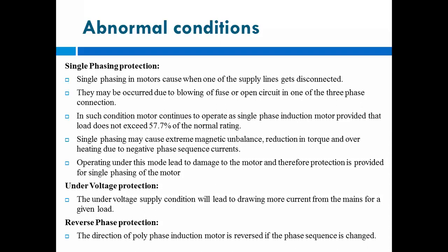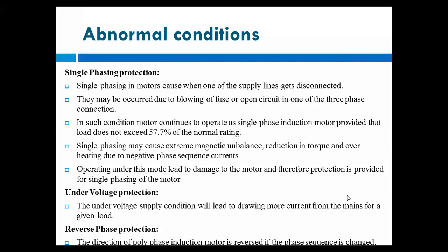And next is the reverse phase protection. Okay, so the direction of a polyphase induction motor is reversed if the phase sequence is changed. I think you have seen the reversal of a motor. You may have performed the practical when the phase sequence changes.